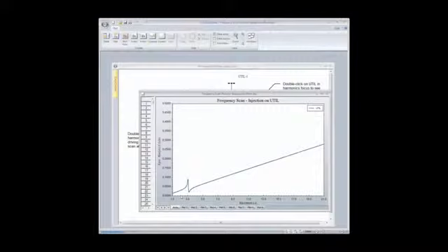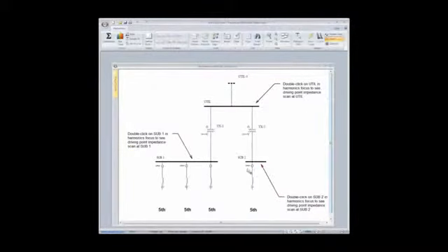So what I have here, looking from the utility perspective down into this industrial system, I pretty much have the ramp interrupted a little bit by the filter down on the secondary bus. Now, what would happen if I had two harmonic filters on two separate supply transformers? What would I get?